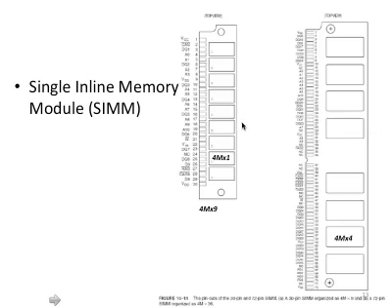So altogether, we have 9 of them. Now the reason we have 9 is, well, we have 8 of them for a byte, right? Because each chip will output a bit. So together 8 chips will output a byte. The 9th one is used for error checking. It's going to do the ECC error checking to verify whether these chips are outputting the right data or not, whether any corruption happens or not.